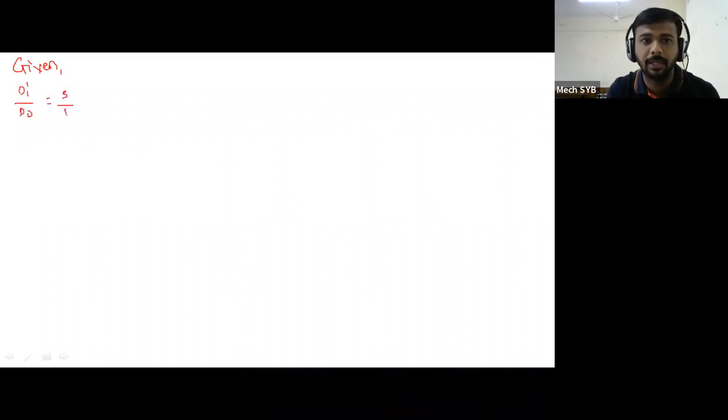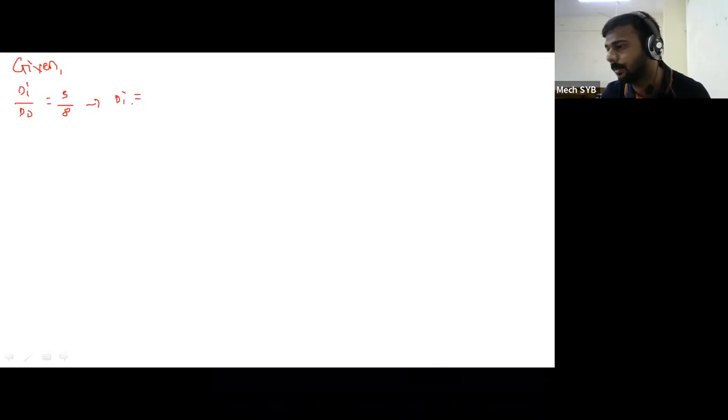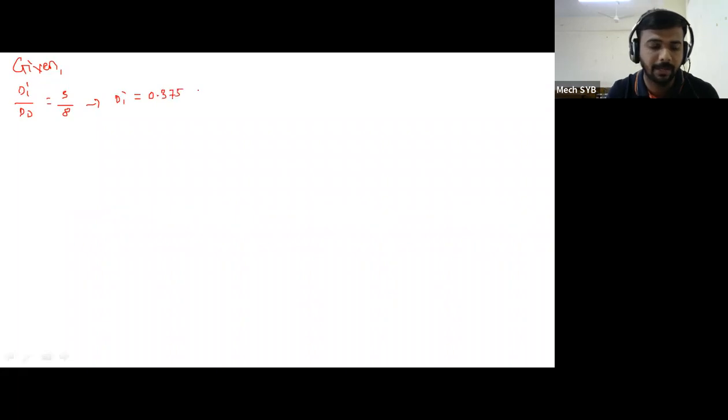Okay, so first of all, I will write down all the given parameters. See, you also start writing the given parameters simultaneously. So first, di upon do is equal to 3 by 8. Then tell me the value. Di is equal to 3 by 8, what is 3 by 8? 0.375. Take all the values, 3, 7, 5. Di is equal to 0.375 into do. This is the relation. Okay.